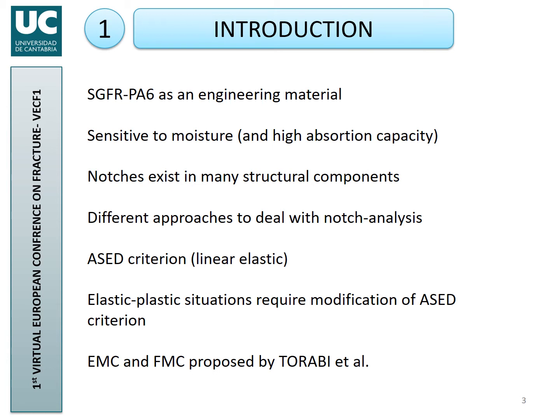There are different approaches to deal with notches, and one of the most extended ones is the average strain energy density criterion, which is a linear elastic method whose use in elastic plastic situations requires modifications, and a couple of these modifications are the equivalent material concept and the fictitious material concept proposed by Torabi and co-workers.